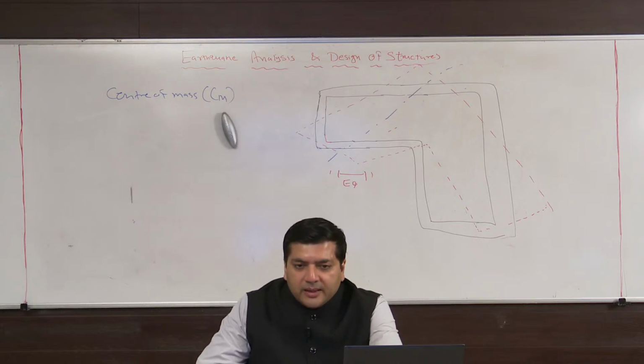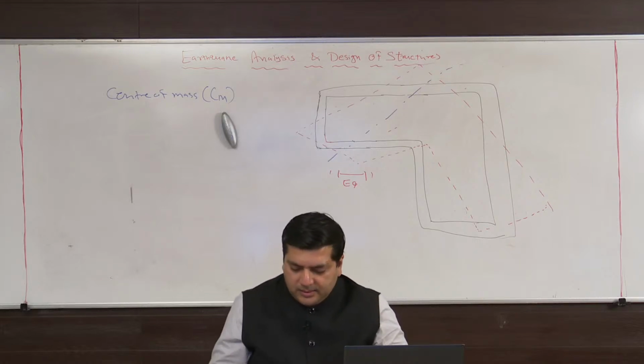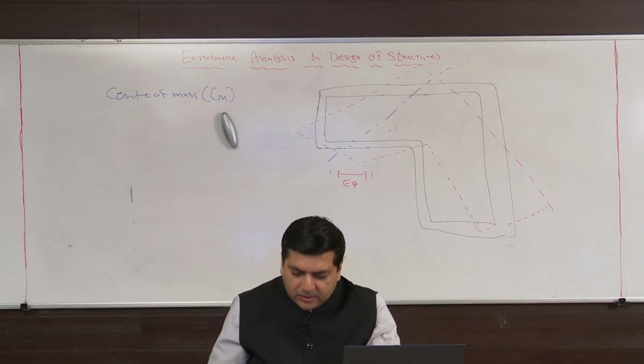This is how we calculated the seismic weight of the building. The floor mass is lumped, right? For each floor we have calculated. For columns and walls, what we did, half above and half below. Do you remember? Yes, sir. So this is center of mass.